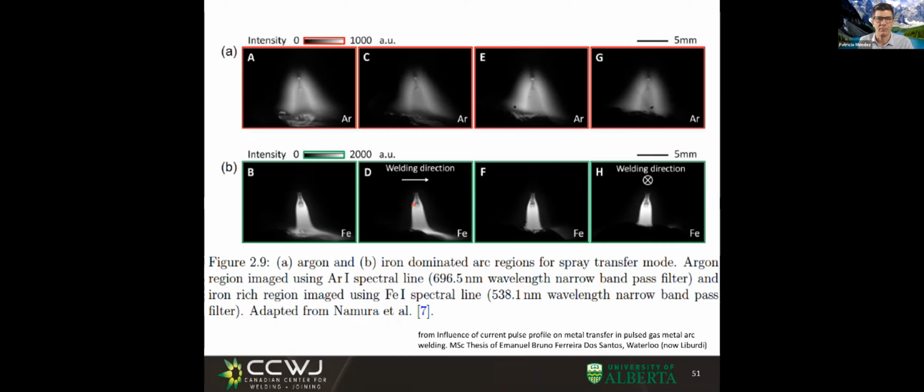A high magnesium alloy, aluminum with a high content of magnesium, looks horrible after you weld it because it's all black. And then you have to clean it up. So is there a way in which we could reduce these magnesium vapors and have less of this smut? Very interesting things, right? That relate to the different plasmas.